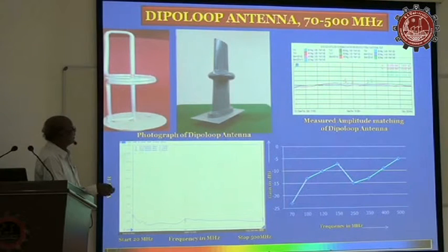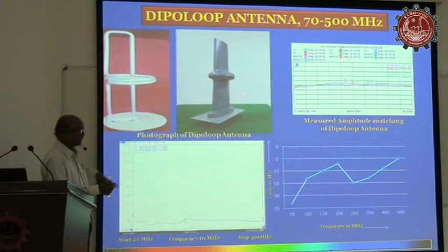We made this antenna, and because we are going to use it on an airborne platform, it should not present any aerodynamic drag. So we made it in the form of a blade, and 4 or 5 antennas are used in combination to make a DF antenna. Another requirement is that the antenna should have good gain tracking and phase matching. As you can see here, they match well in amplitude from antenna to antenna. Now we are going to use this in one of the current EW programs.